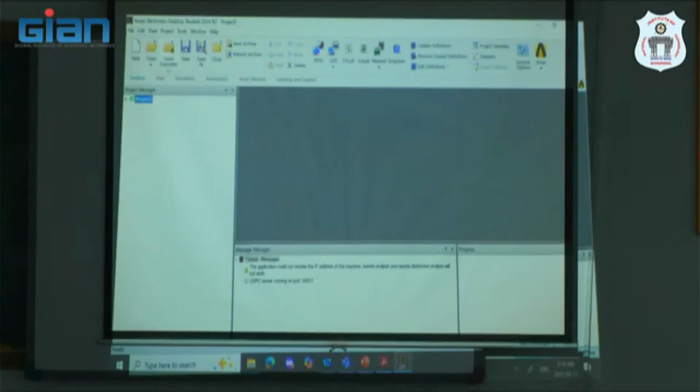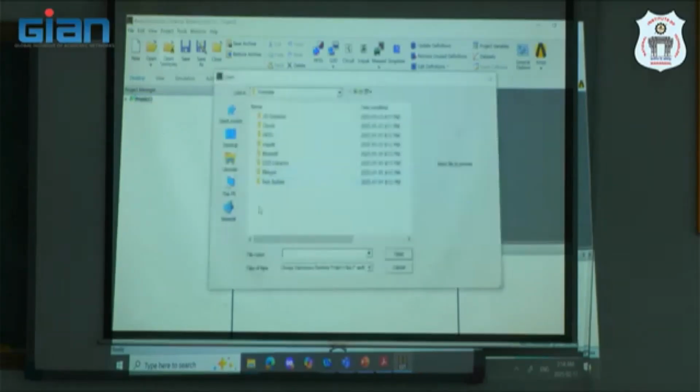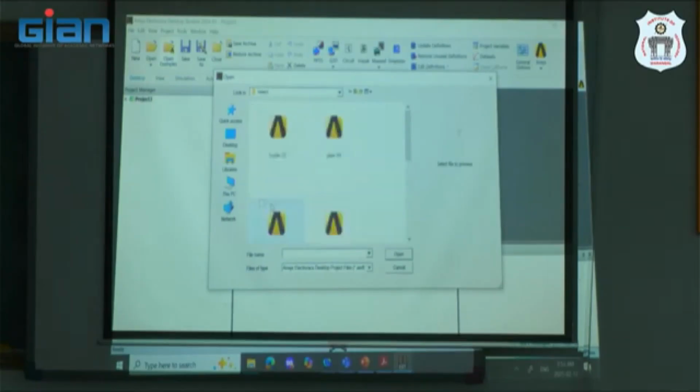So let us open an example, and since we have been talking about induction motors, let's get started with the induction motor. When you click on open examples, it will give different types of tools within the software. We will go into what is called the RMxprt tool. It's a library basically, it allows you to quickly model motors. This has multiple examples. I am going to take induction motor IND-M3, let's say, just a random one.